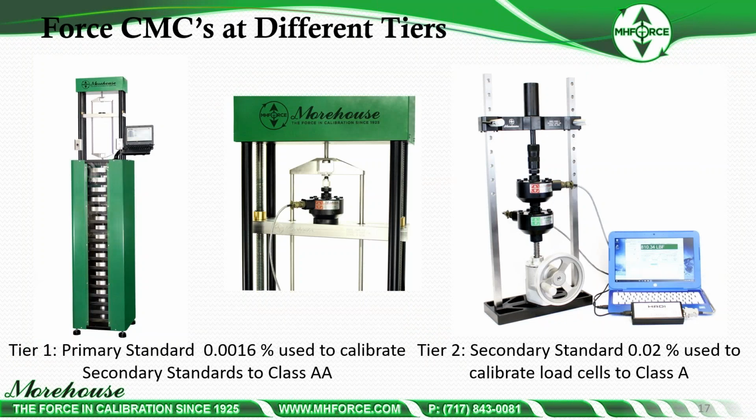So you have 4 CMCs at different tiers. So tier 1 is to the left. There's a primary standard used to calibrate secondary standards. If we're talking with ASTM, we're talking about verified range of forces, and we're talking a class AA verified range of forces. The picture in the middle is a load cell set up in compression being calibrated in a primary standard machine. Then that load cell gets used to calibrate other load cells. We have a class AA device, or we have a tier 1 calibrated load cell. It gets put in the machine.